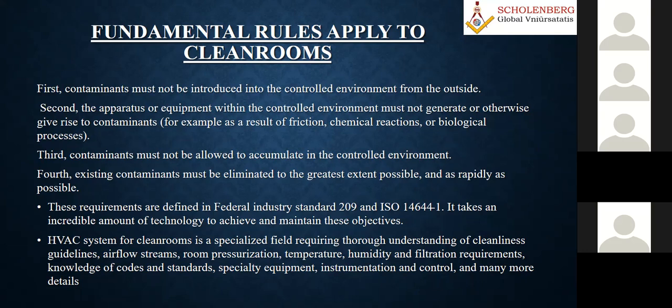These requirements are defined in the federal standard, and it takes an incredible amount of technology to achieve and maintain this objective. So the HVAC system is a very specialized field requiring a thorough understanding of cleanliness. As I told you, we have the federal standard, we have the ISO standard, and various ASHRAE standards, 62.1 or 170 for healthcare, even 90.1 and ASHRAE standard 55, but it's a very specialized thing.